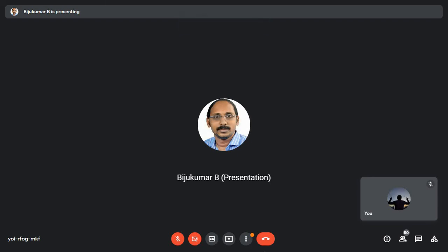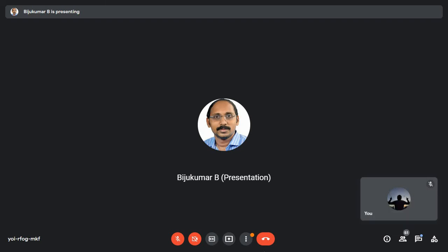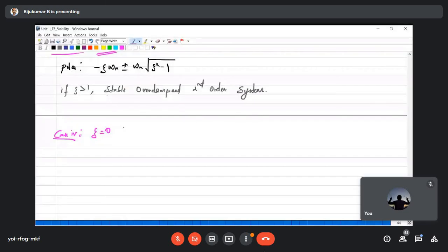Now, one more case is there. What happens when zeta is zero? What are the poles? Minus zeta omega n will become 0. There is no real part. What about the other part? It will become plus or minus omega n root of minus 1.